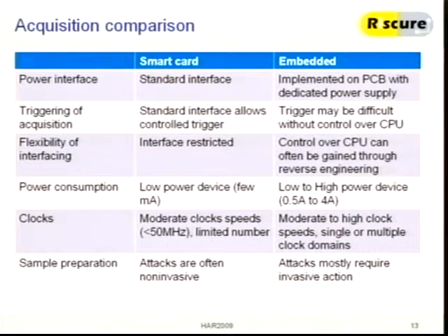One of the attractive things in an embedded system is that if you can customize it, it can often run much, much faster than a smart card. For a DPA attack, you need measurements, and to overcome noise, you need a lot of measurements. We have done 5 million measurements or more in a day on some chips, whereas for a smart card that's maybe a week or more. So some things actually work to your advantage.